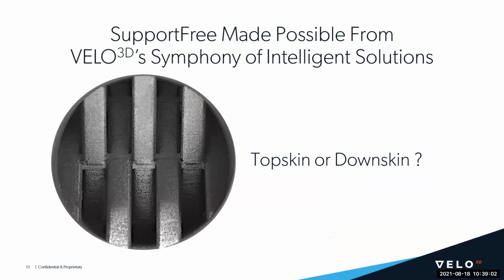This is actually a picture of the downskins of the baffles. Typically in metal additive, if you have downskins, they can be excessively rough from breakdowns, or they might have support contact points that need to be ground away to end up with a decent surface finish later.